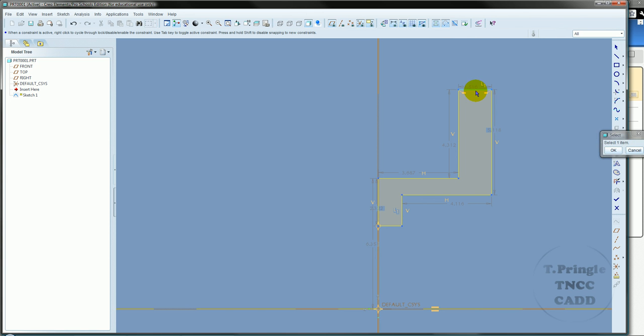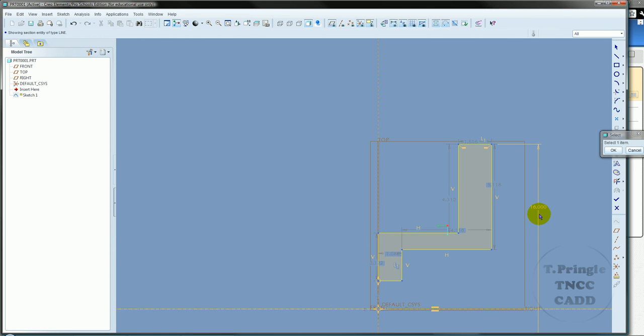If I click on the dimension tool and then I click the top line, the geometry center line, and then the top line again, when I place my dimension, it's going to ask me for a diameter as opposed to a radius like I would be getting any other time. This is going to enable me to not have to do quite as much work in the math area to get everything dimensioned that I need to get dimensioned. So that's going to serve as a really good purpose for having that geometry center line in place.